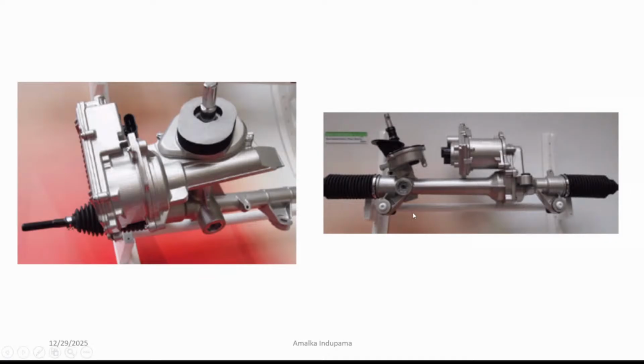So I'm mainly referring to the EPS. The EPS has a separate ECU. That ECU will send a signal that the vehicle speed is now lower, so they reduce the steering effort by providing higher torque to the wheel. But at highway speeds, the motor torque will be reduced just to maintain a uniform direction by tightening the steering system.